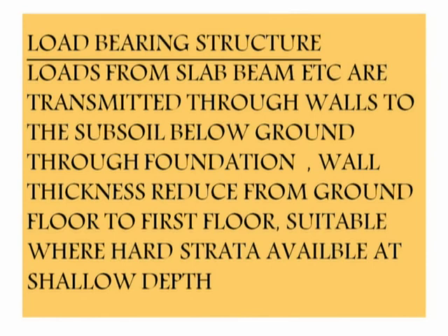This load of the building is to be transmitted to the lower ground. That means that the load is to be transmitted to the foundation. In case of the load-bearing structure, the loads from the slab, the beam, etc. are transmitted through walls to the subsoil below ground through foundation. Means the transmission of the load from your walls to the foundation. So the transmitting agent is the wall.